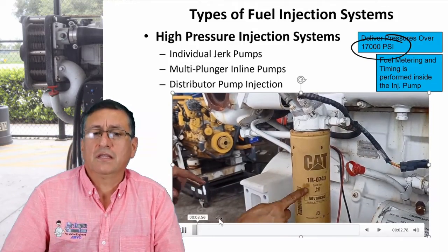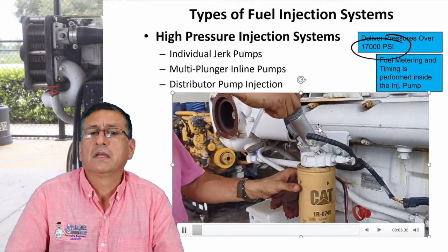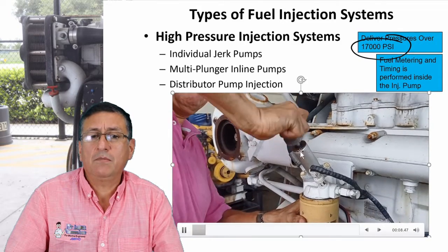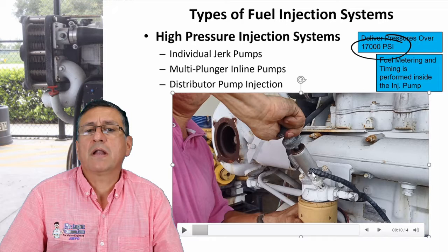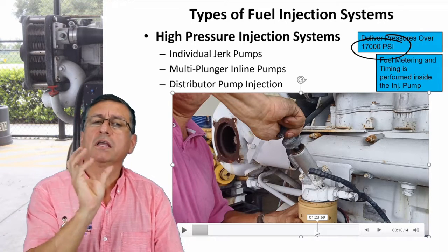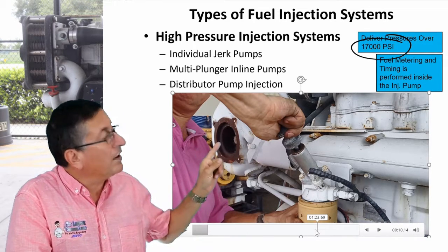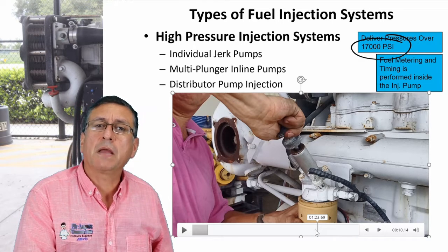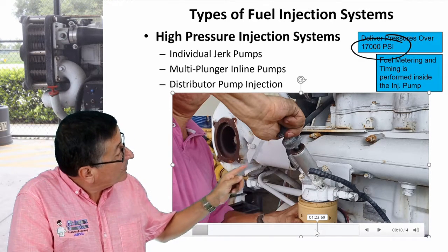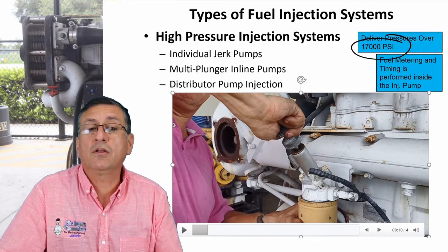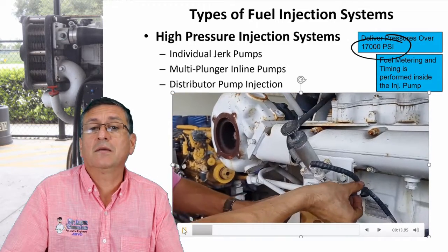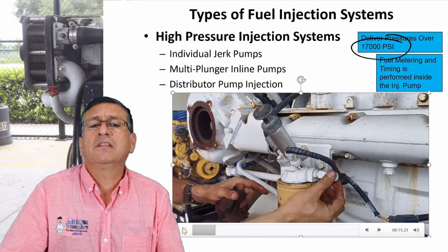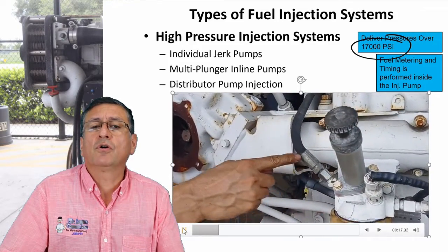Okay, this is the fuel filter. This is the handle. You remember the name of that pump? This is the priming pump. It's located in the bracket where the fuel filter is bolted. In that bracket you have the priming pump, and on the side you have the bleeder in order to bleed the system to eliminate bubbles. Yes, this is the bleeder, correct. There you bleed the system and the fuel continues.